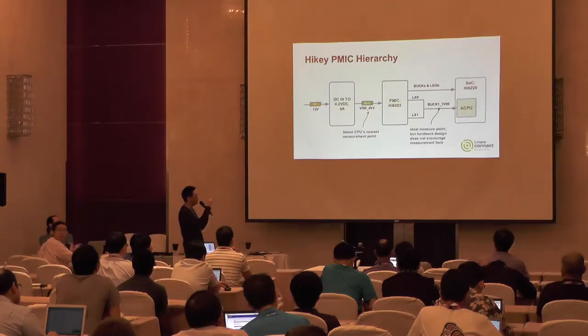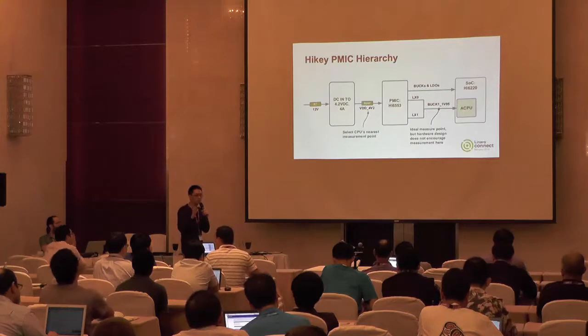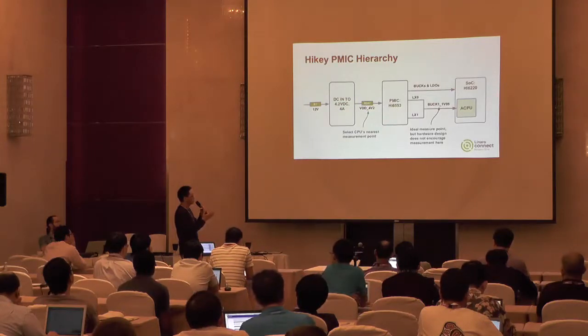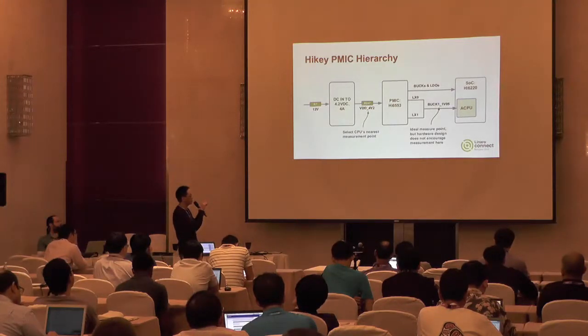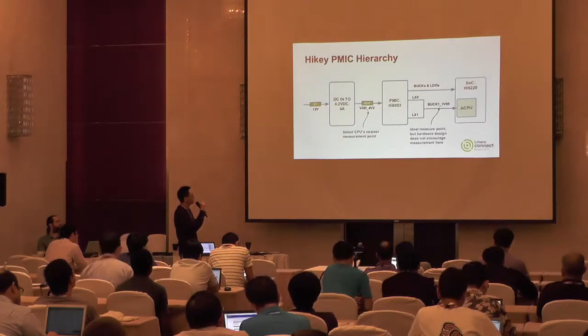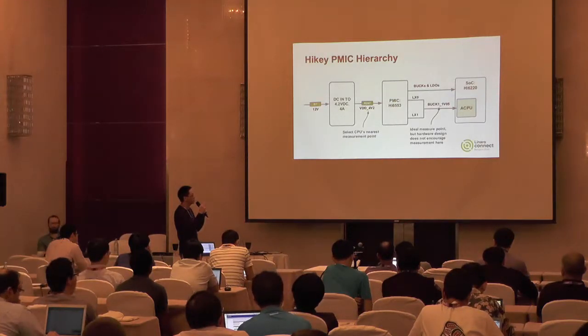There it has a power domain, the ACPU, which is the CPU part. Then the PMIC is also a HiSilicon PMIC. It outputs many bucks or LDOs to supply power to the SoC. There is a dedicated Buck1 that outputs to provide power supply only to the CPU part.